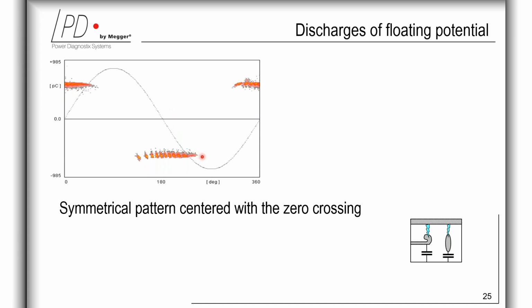Here, as soon as the critical field is reached, the electron avalanche can start and a row of pulses of even amplitude is generated. And this setup produces discharge pulses whenever the electric field is changing. For this reason, the activity starts at zero crossings, but leaves the 90 degrees and 270 degrees area unoccupied. And this is actually very similar to the concept with high electron availability that we have seen in the previous slides.